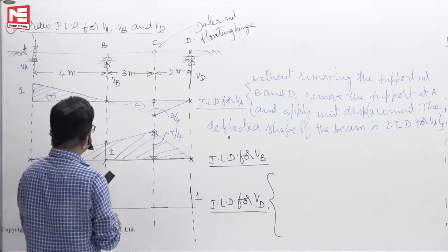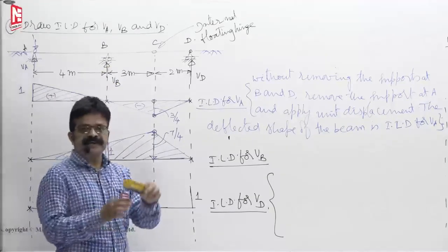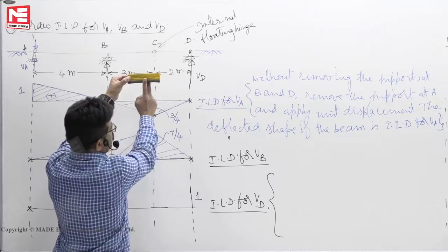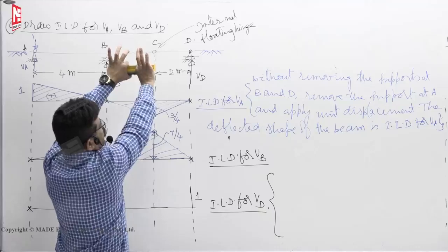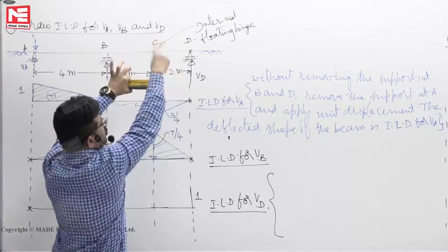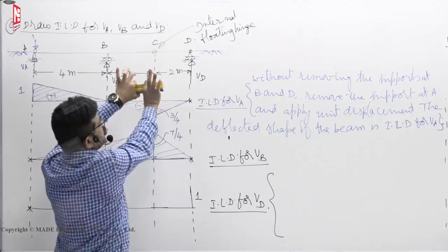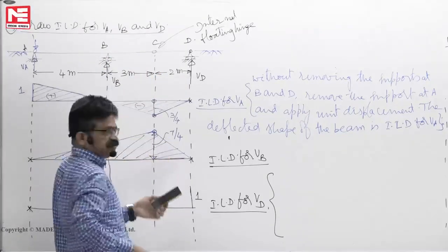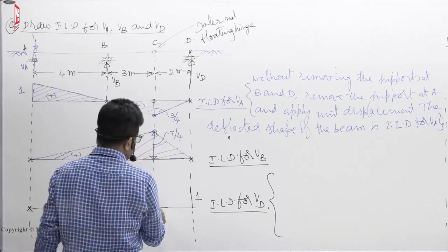the deflected shape. Now you see, when you lift there by 1, A and B cannot be lifted. See here, this is the beam, let us say. Where I am holding is A, this is B. This point is C. At two positions, I hold it tight like this. Don't permit the beam to lift at A and B locations. Can C be lifted up? Without bending or breaking, I cannot lift C because I am holding at two locations like this. Then this cannot be lifted. Instead, if you have to lift it, I must bend it, which we should not do.